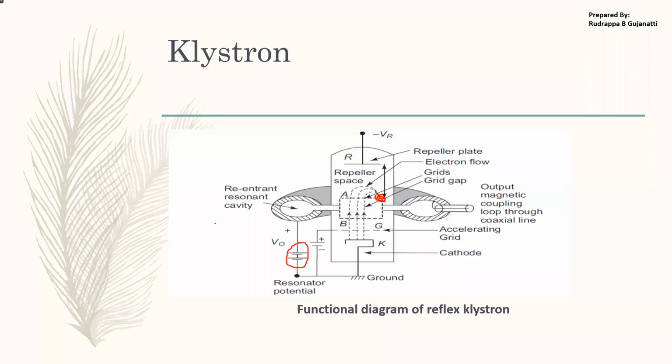So since the resonant cavity is applied with the DC voltage and noise is present in this resonant cavity, a microwave AC signal is generated. Because of this bunching of the electrons and the noise which is present over there, we'll be able to get oscillations in the range of microwave frequency. So these interactions help us to achieve the microwave signal. This is the overview of its mechanism. This is what is happening in the microwave devices.